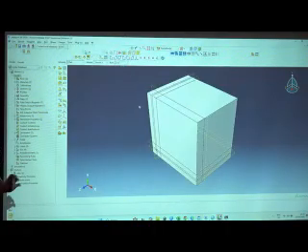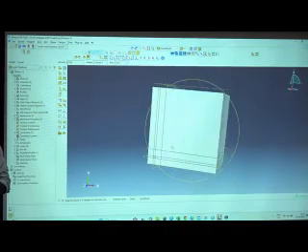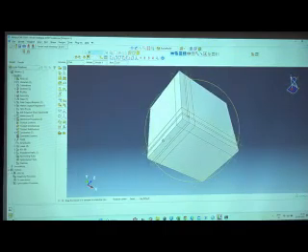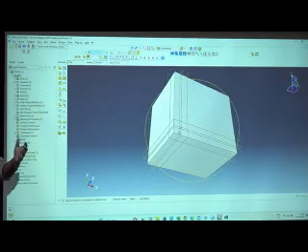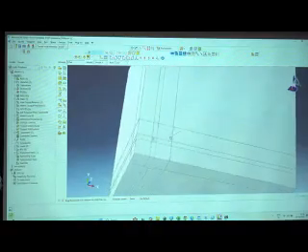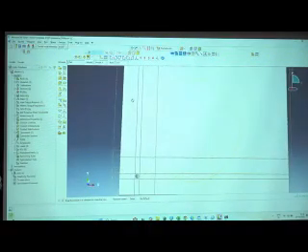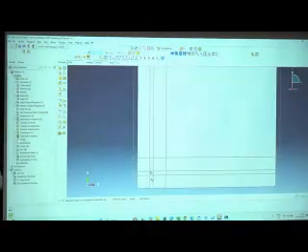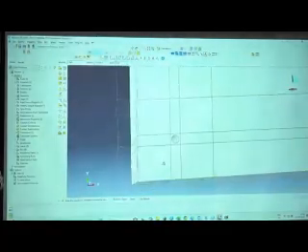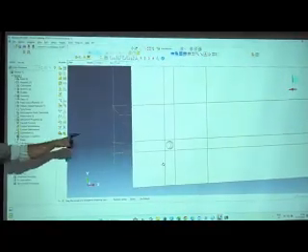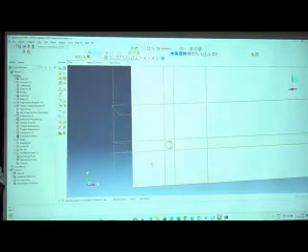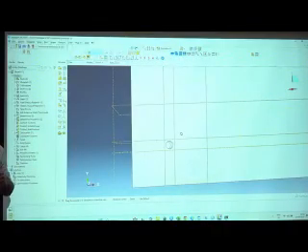So this is a soil profile. You can see that I have done this partition before the assembling. So this is the pile hole. Okay. So this is the location of the pile under the raft. This is the center point. The pile is at this point. So we are simulating this part only.